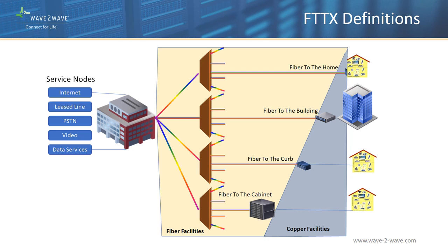There are also other common subsets of FTTH, such as FTTN, or fiber to the node or fiber to the neighborhood, FTTP, fiber to the premises, FTTB, fiber to the basement, etc. The FTTH network will have large fiber counts for accessing as many homes as possible. For instance, reaching a neighborhood of 3,200 homes, an outside plant cable would minimally require 100 fibers, one per 32 homes, based on full utilization of the 1x32 optical splitters used in the outside plant distribution.